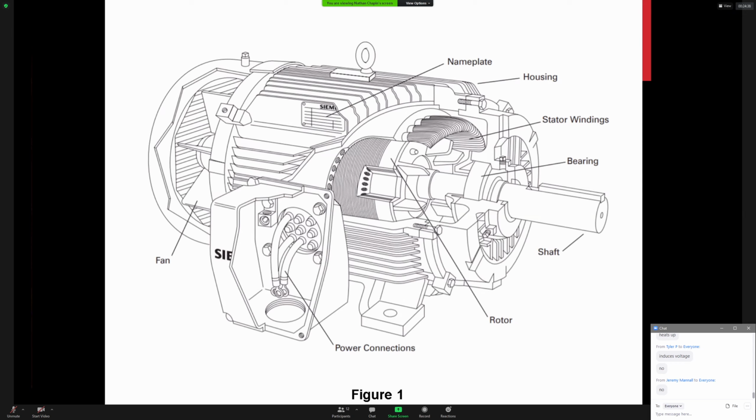And the answer is no, of course not, right? This is one of the problems that we have associated with variable frequency drives that is easy to overcome. But when we run a motor at a very reduced speed, what happens is this fan becomes inefficient. So there are some inverter rated motors that have a totally separately powered fan here, run on an external circuit. So no matter what speed the rotor is spinning at, the fan is spinning at a speed that is equivalent or capable, we should say, of cooling this whole piece of equipment down.